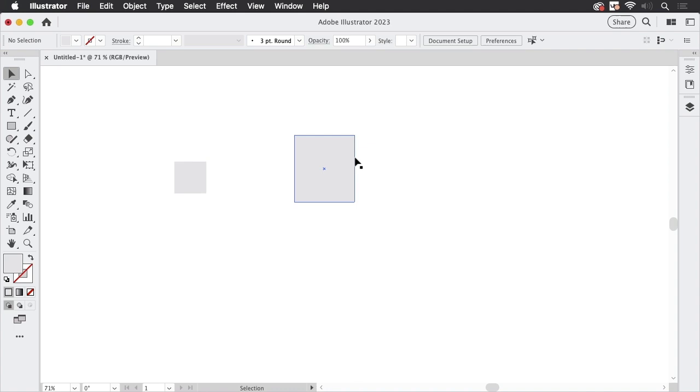And you might be able to find paths and anchor points without using smart guides, because it's obvious, and also the cursor shows it. You see the change in the cursor symbol, and then there is this path. But there are some things that only smart guides show.